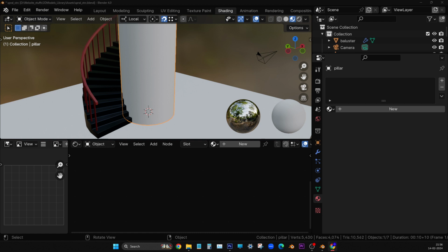Now you can increase reflection nicely so that it will be seen, metallic or whatever. There is another way of reflection also, I will show you later, but for now we'll manage with metallic. However much you increase the metallic, it is not showing any effect. You may wonder why. The cause is that roughness is always there as an obstruction, so we have to decrease it. Now you can see the effect of metallic.